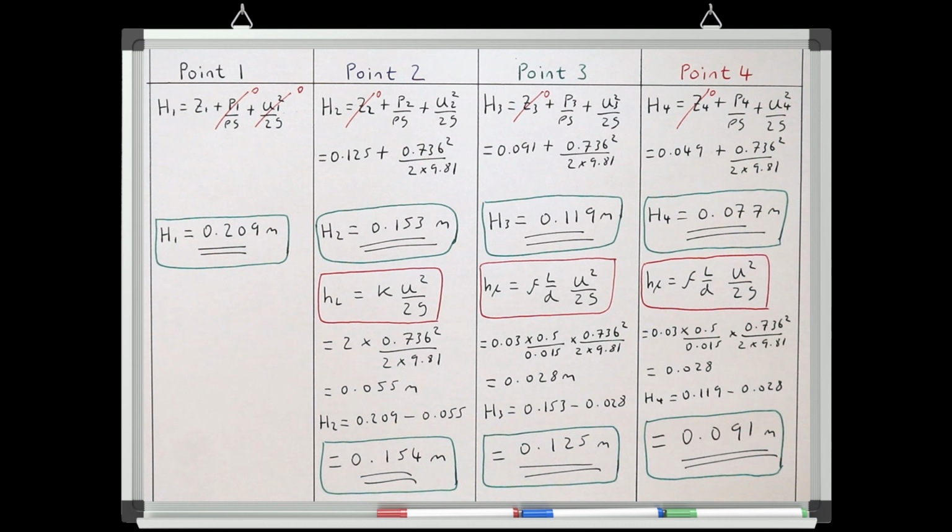When I was looking at the system after the tests, I discovered that despite my best efforts, the final part of the pipe wasn't exactly level, and this leads to a small offset on the pressure gauge, which has caused this inaccuracy in the final result.